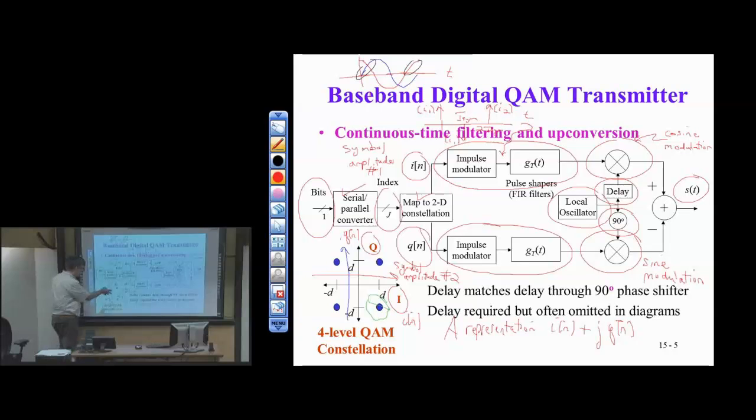So if I think about phase error, just rotate the constellation by that phase error. If I make a 90 degree phase error, it's like rotating this thing 90 degrees. Everything's wrong. All the symbols are in error. Now, if I rotate by 45, I might be okay. I'm on these threshold boundaries for detection. If I rotate by, say, 20 degrees, I'm probably pretty okay. Okay, so PAM, this is 4QAM. The higher the constellation, the more sensitivity I have to phase. So phase now becomes more and more significant to worry about in the receiver.